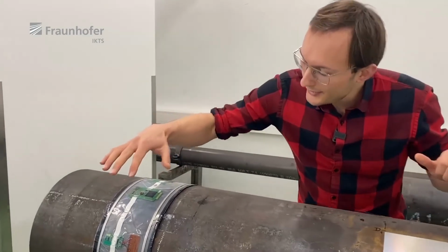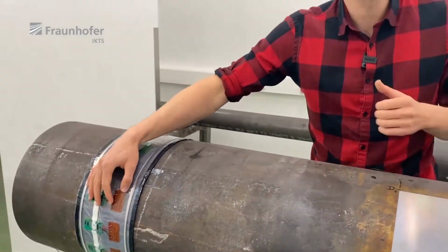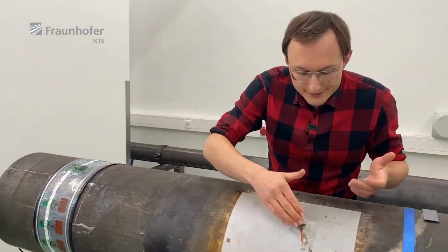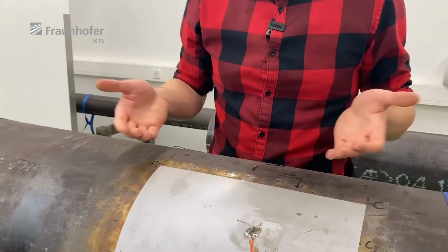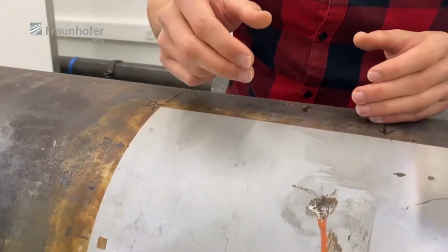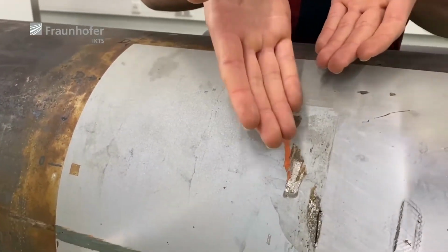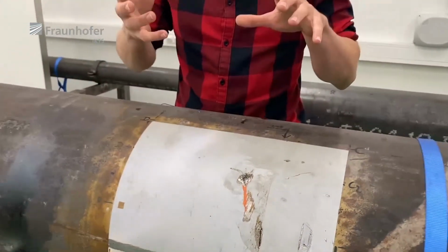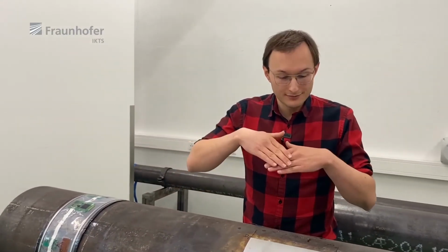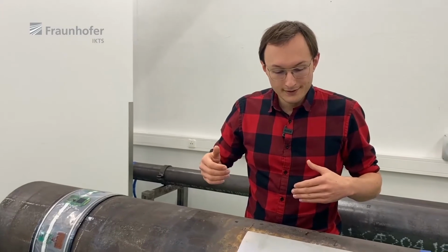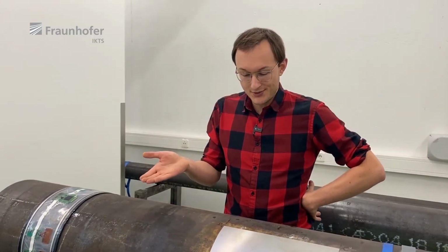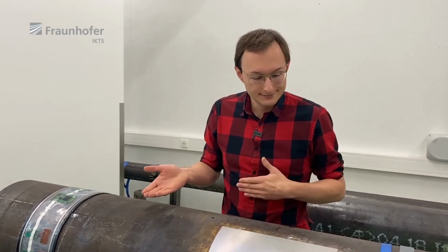So we configure one of those nodes as the transmitter. Then the wave goes to a crack. What cracks can that be? Actually anything. It can be a crack like this. It can be corrosion where the pipe became thin. It can be sediment where the pipe became thicker than originally. There are actually pipes made of carbon fiber composite. They suffer from delaminations. We can detect that.